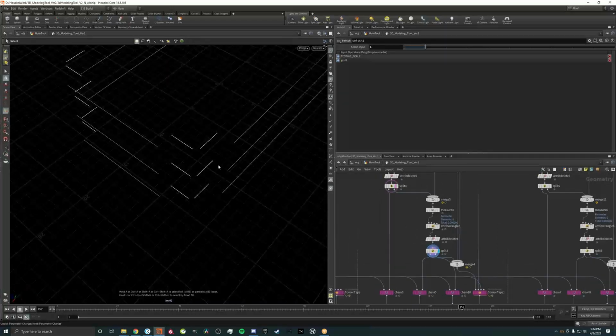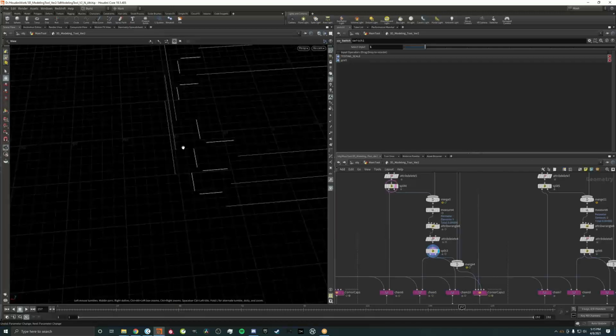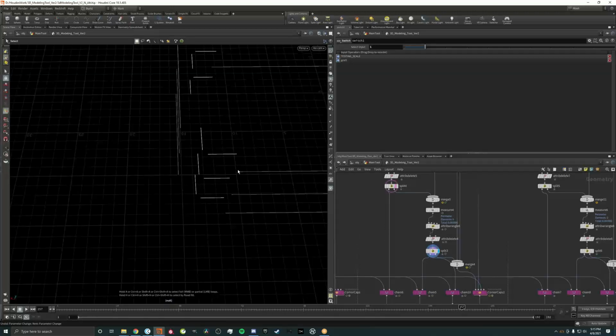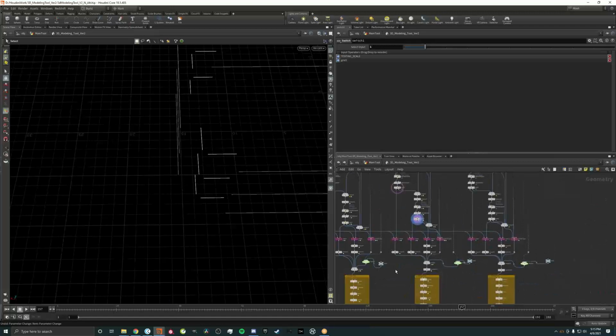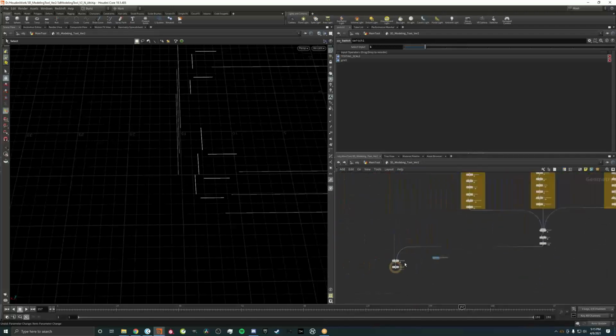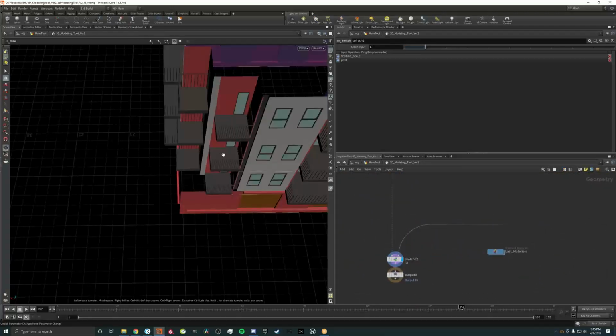depending on the type of departure we have on the corner, Houdini will move those actual pieces, because it builds the facades based off of lines. So it moves those actual pieces back in its own little space. Move it back too far, then it collapses and we have no corner, and Houdini will fill in the rest.